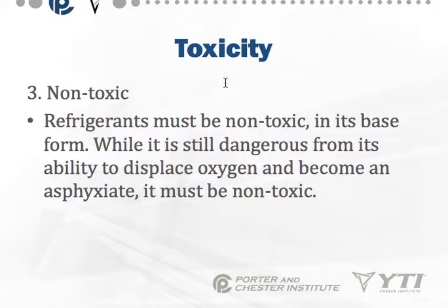Refrigerants have to be non-toxic, okay? While it's still dangerous from its ability to displace oxygen and become an asphyxiate, it has to be non-toxic. Okay, in other words, you cannot have lingering health effects that increase over time with exposure to refrigerants. Again, you don't want to breathe it in because it will drown you because it displaces oxygen, but it cannot have toxicity.